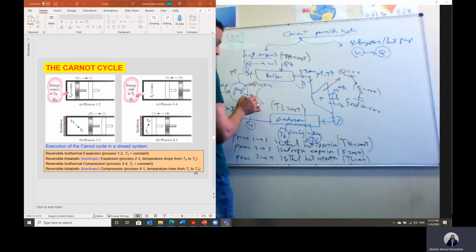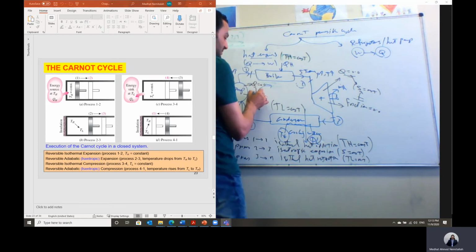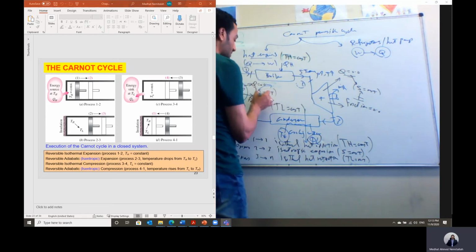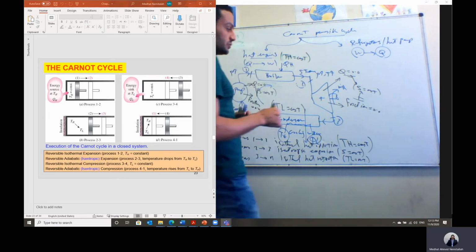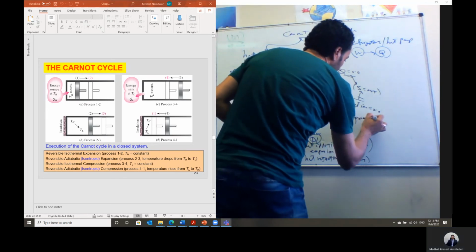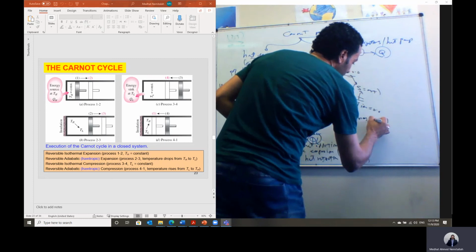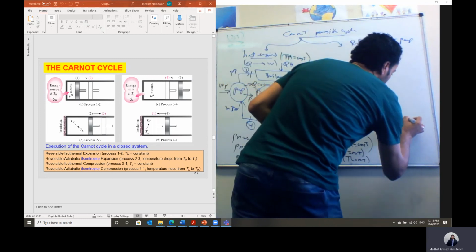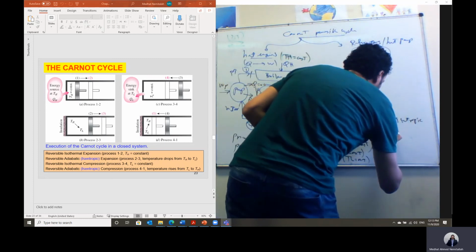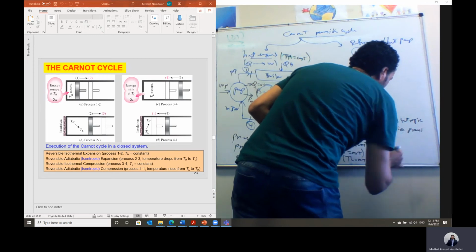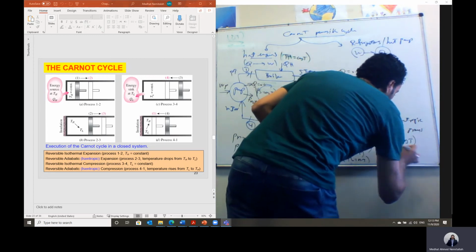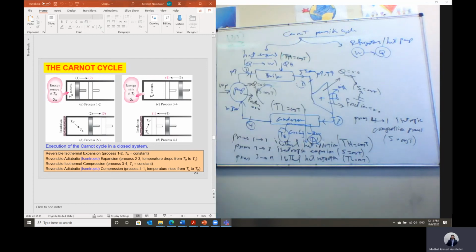We should not have heat lost, and the friction should equal 0. Adiabatic and frictionless means the compression inside the pump should also be isentropic. So the process from 4 to 1 is an isentropic compression process, and the entropy would be constant.